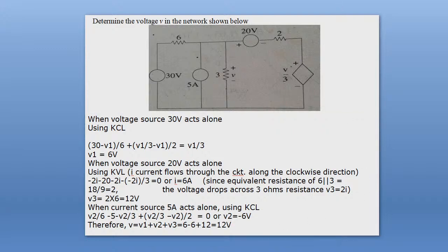So therefore we can solve circuit theory problems associated with dependent sources as well as independent sources, current source, voltage source, whatever, by using the superposition theorem. But for this case we need to consider independent sources one by one, while dependent sources will always be present in our circuit with independent sources.